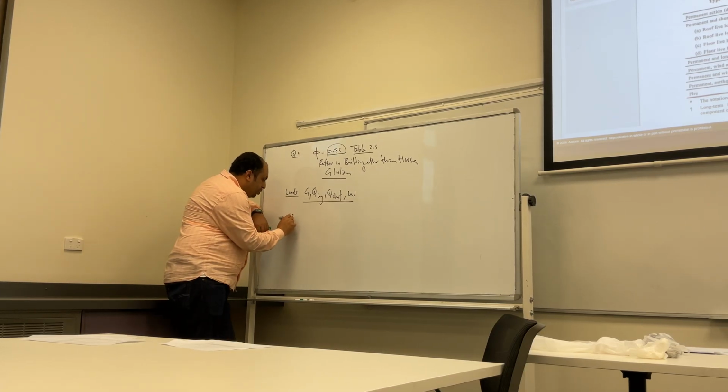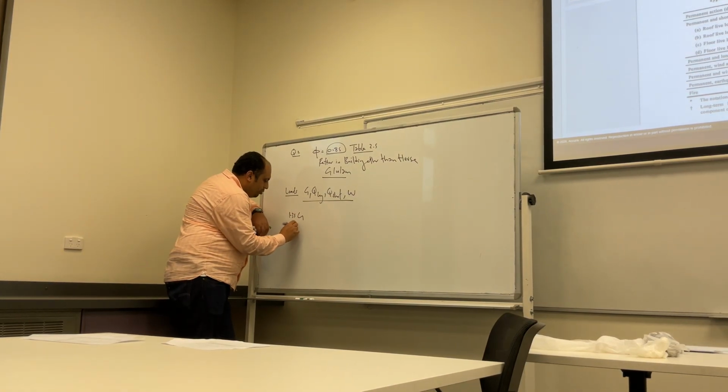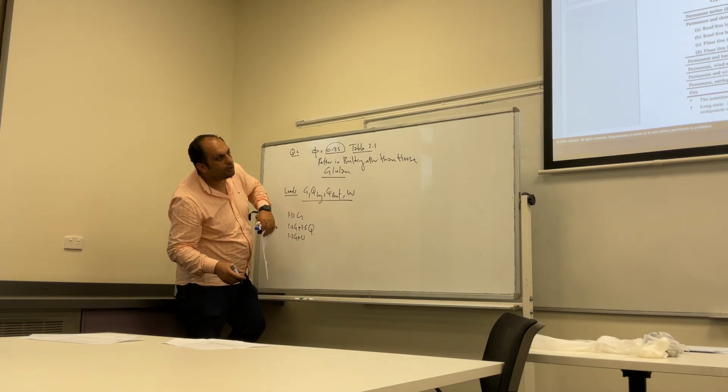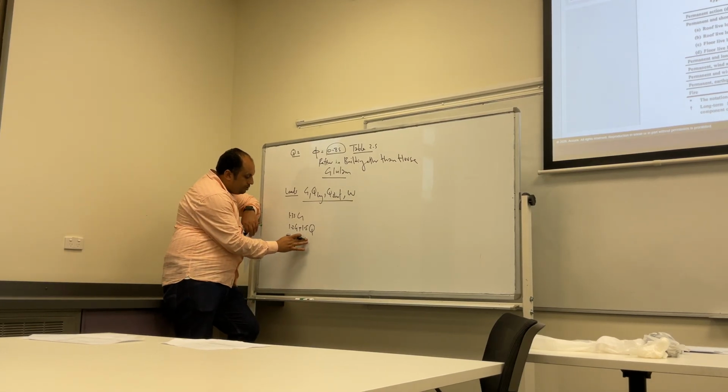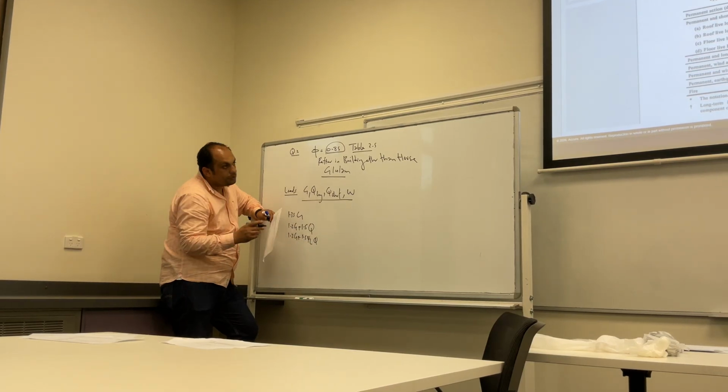So how many load combinations? 4. 1.35 G, 1.2 G plus 1.5 Q, yep. 1.2 G plus psi L Q. What else?